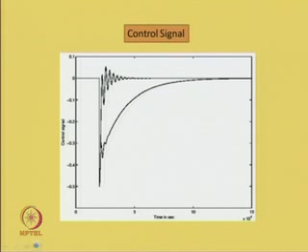The control effort one has to provide with the inclusion of the noise filter in the loop is very less. If you see the excursion, the amount of energy you spend is very less compared to the earlier case. You take the area of the lower curve and the area of the upper curve, below and above the 0 line, and that gives a significant improvement in the second case.